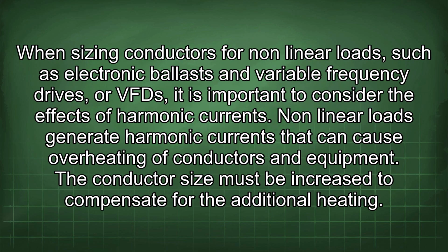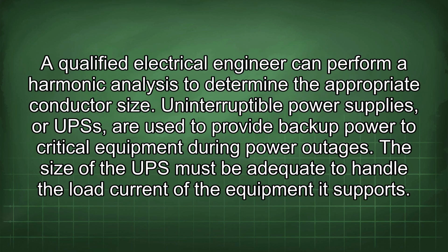When sizing conductors for nonlinear loads, such as electronic ballasts and variable frequency drives, or VFDs, it is important to consider the effects of harmonic currents. Nonlinear loads generate harmonic currents that can cause overheating of conductors and equipment. The conductor size must be increased to compensate for the additional heating. A qualified electrical engineer can perform a harmonic analysis to determine the appropriate conductor size.